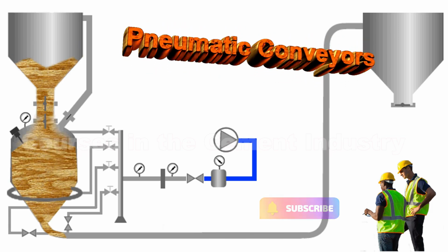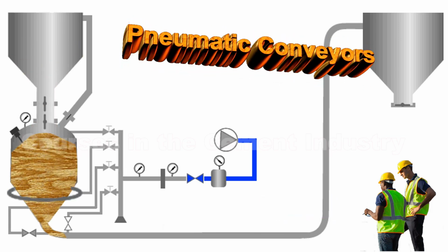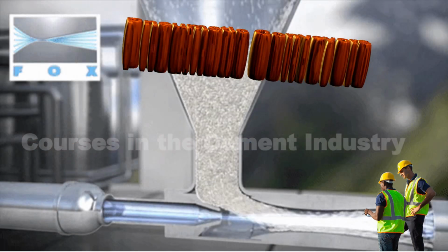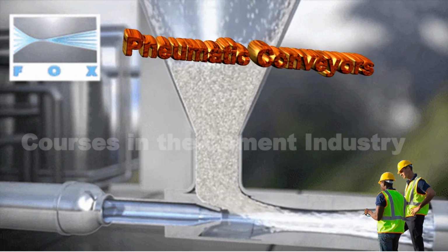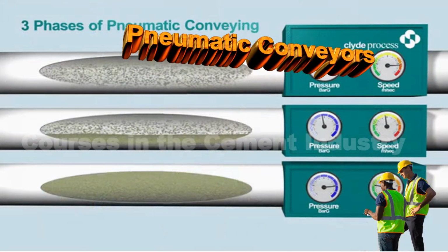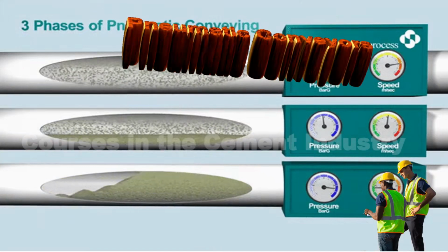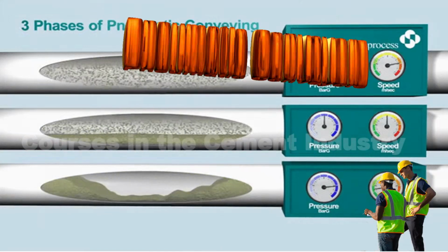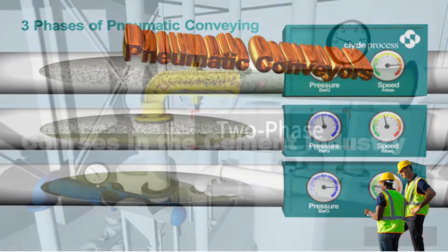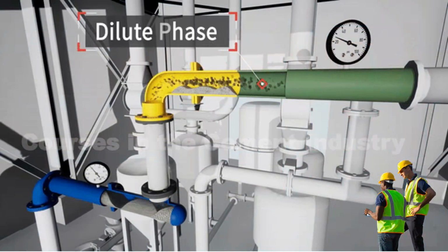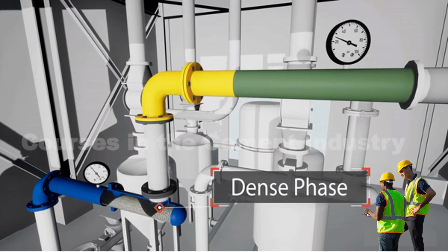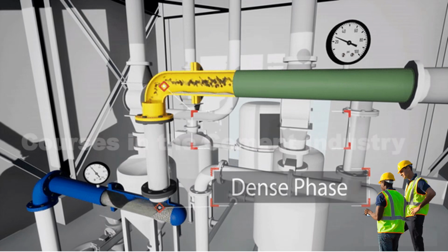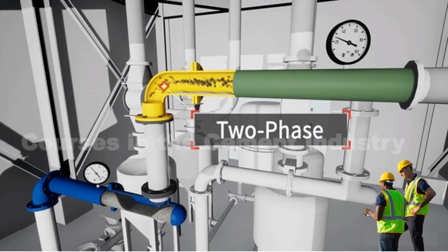Pneumatic conveying is based on the physical principle that air, under certain conditions, is able to convey heavy materials. In nature, air can carry many substances, such as sand, cement, snow, leaves, and seeds. Pneumatic conveyor types are defined based on what kind of material is movable, and their source of airflow. The three main pneumatic conveyor types are dilute phase, dense phase, and semi-dense phase conveyors, where each can be pressure or vacuum driven.